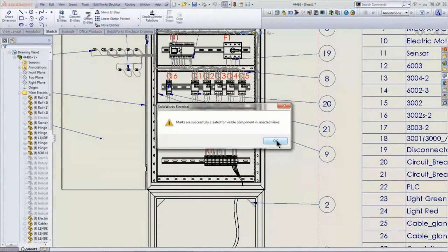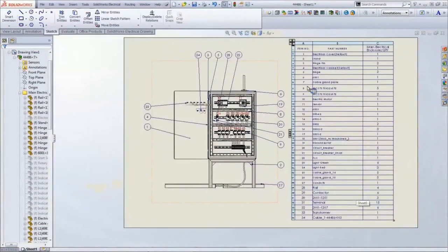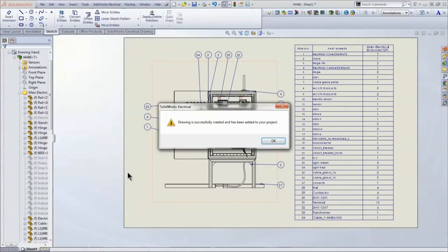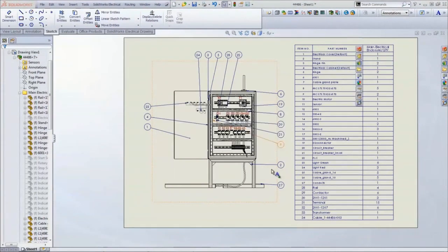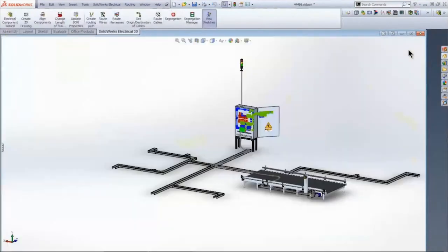So you can also generate a drawing of this. What this is doing is generating the drawing into the project with the bill of materials. You can go ahead and generate this, and it will add it to the project that is in the specified folder. With this, you can also create multiple sheets and export them at the same time into your project folder. No need to do anything manually or click and drag, it's all automated.